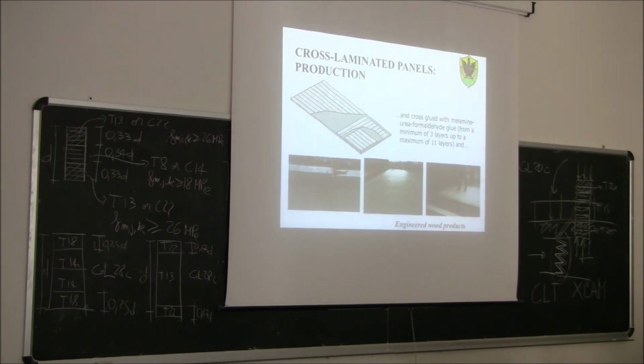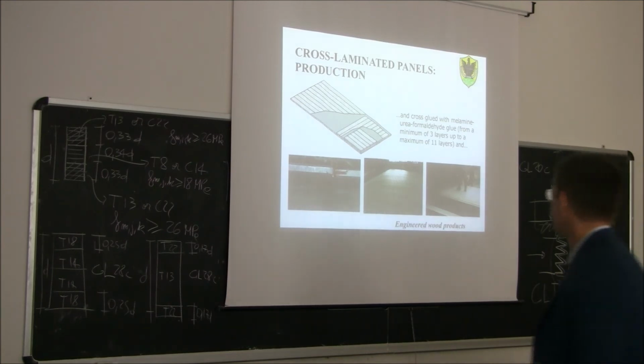And they are cross-glued with melamine urea formaldehyde glue, from 3 layers up to 11 layers. So we can have 5 layers, which is the most common one, perhaps this one, 5 layers. But we can have a layout from 3 layers up to 11.